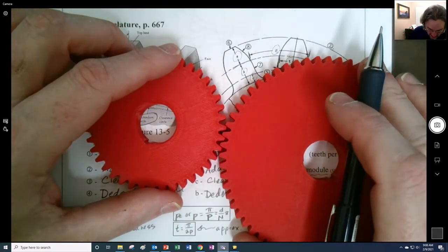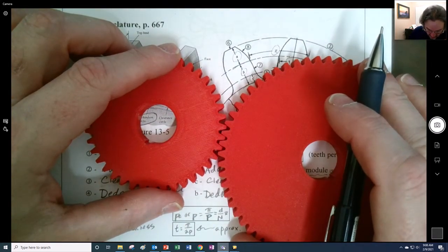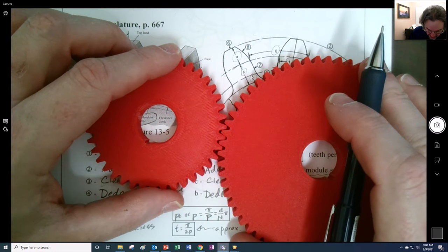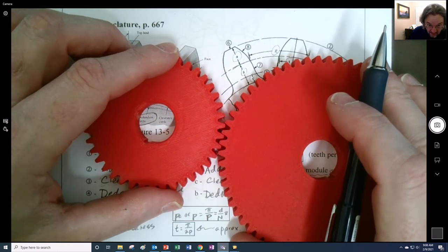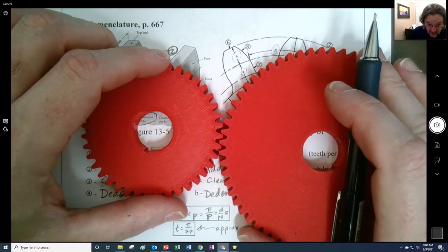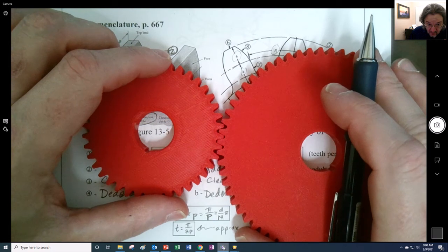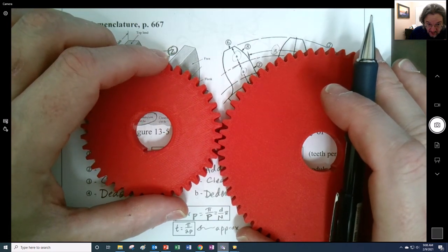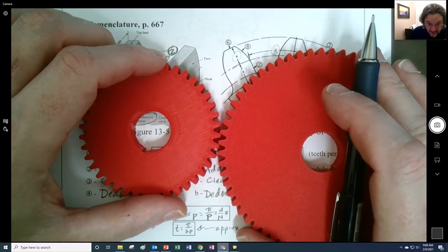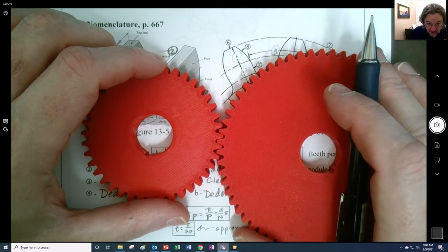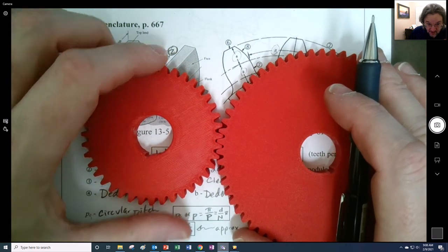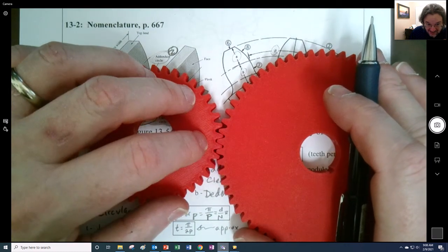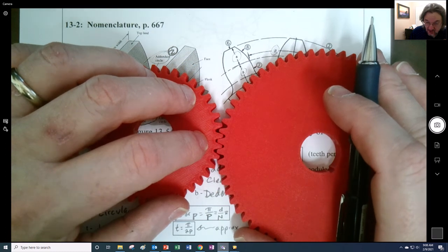If it actually was exactly perfectly there, we wouldn't be able to have some amount of flexibility of the center of the shafts, how far they get away from each other, right? And we'll actually have a little discussion of that. But if there was exactly the tooth thickness, you wouldn't have anything.